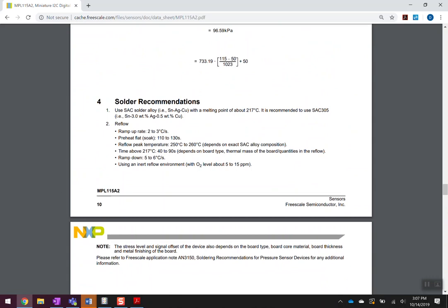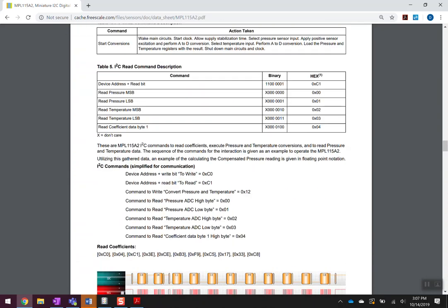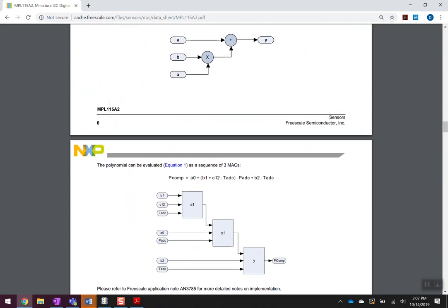I2C bus. The advantage to that is instead of having to use up a bunch of pins for all of the communication to various sensors that you're connecting up, you basically get to just connect everything to the same 2 pins. That's the advantage of I2C, is you can connect multiple devices up in a master-slave configuration.